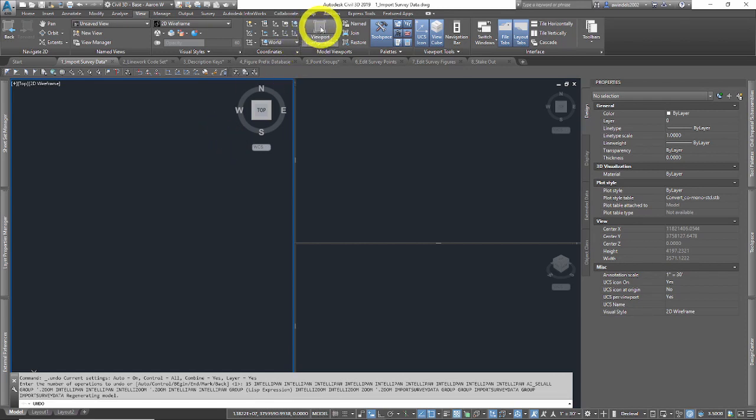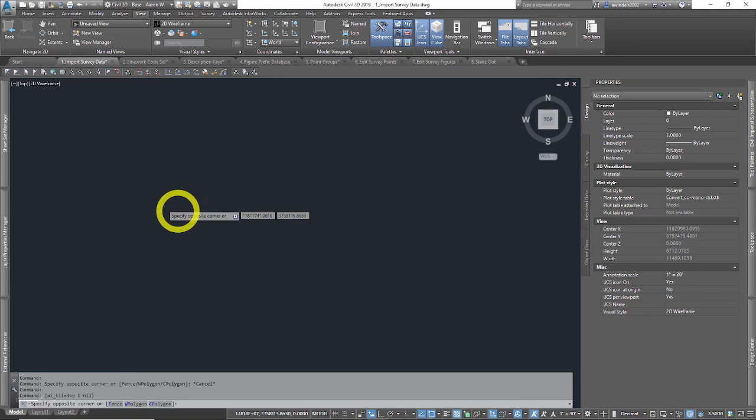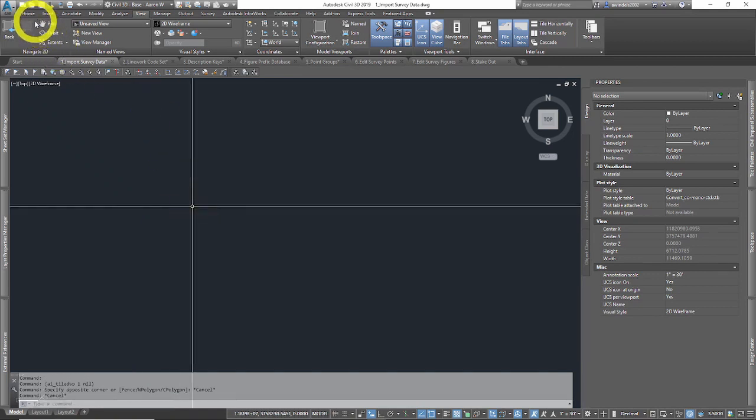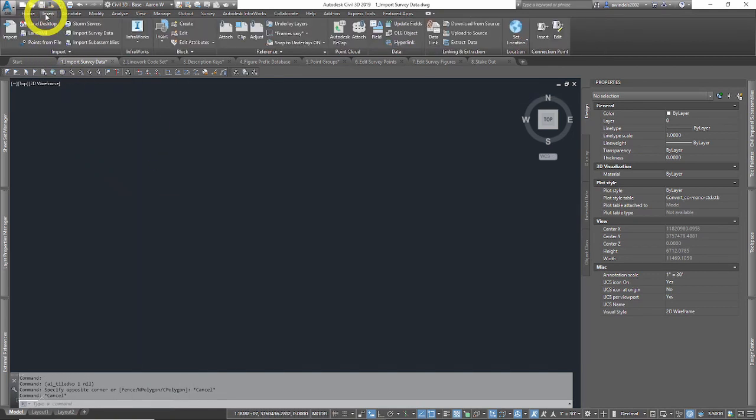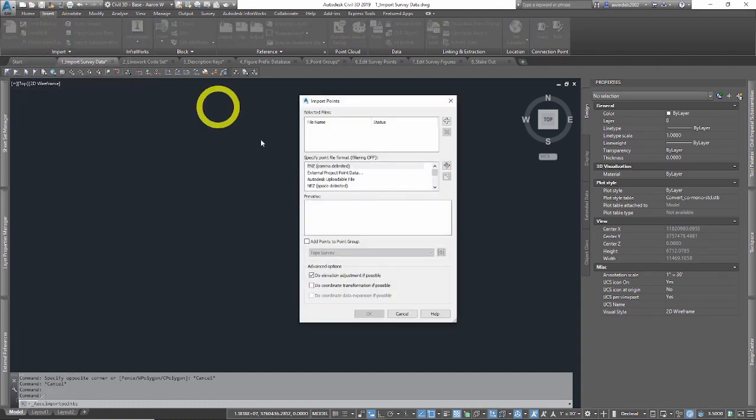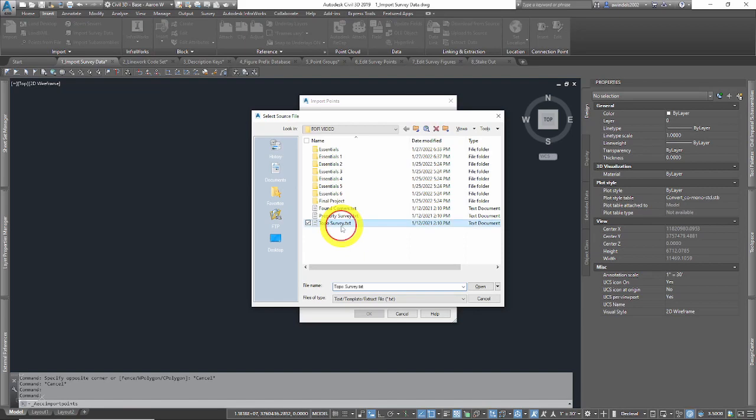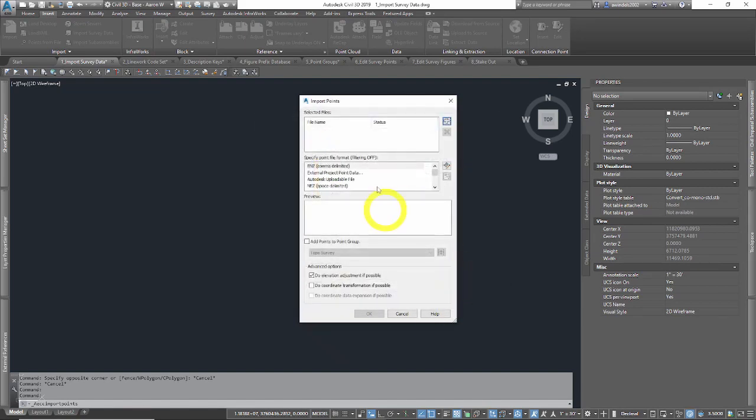It didn't. I'm going back to one viewport. I'm going to show you a quicker way to import survey data, more quick and dirty without too many bells and whistles. On page 44 it says there's another way. You can do insert, points from file, and now we'll search for that same point file in my chapter 3 files, TopoSurvey.txt. It should queue us up there because we've already been there. Yep. Open. Let's change the point file format, which is, we found out, important, how the points fall.